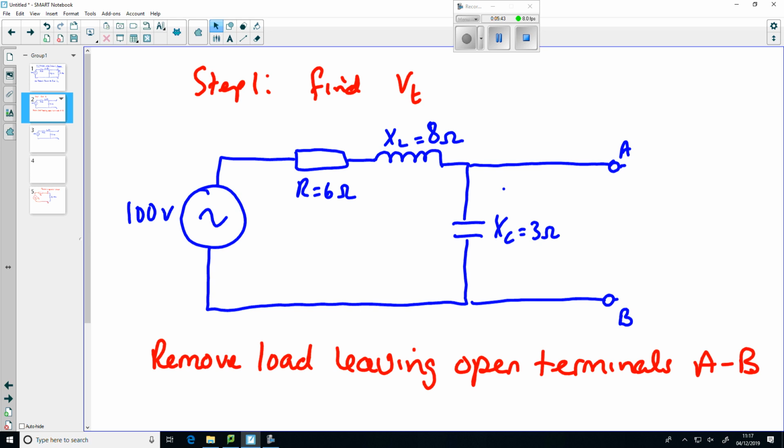You do need to know this process, because in an exam question about Thevenin's, I'm going to be expecting you to properly explain the process and not just do it. The Thevenin voltage is this voltage here when the load resistor is removed, the open circuit voltage. So that's Vt across there, the open circuit voltage when the load resistor has been removed.